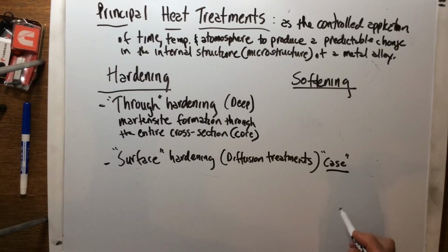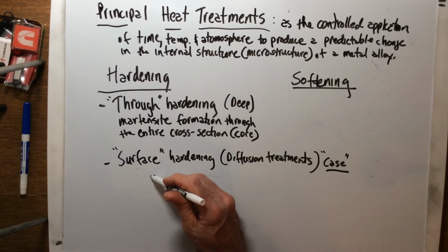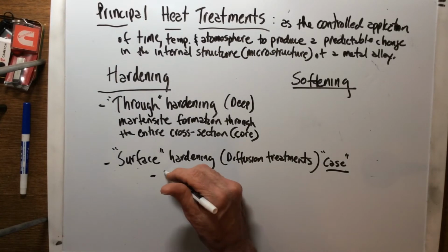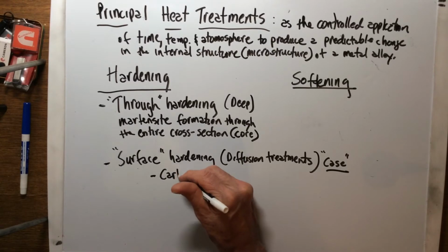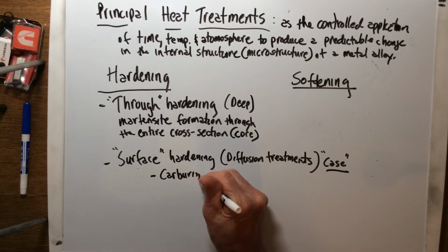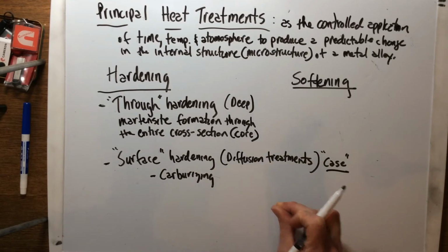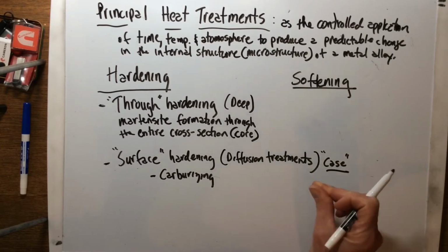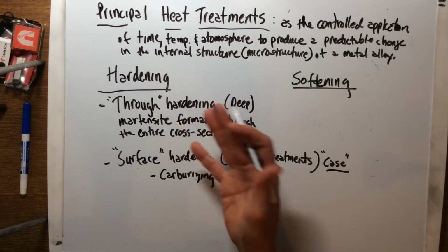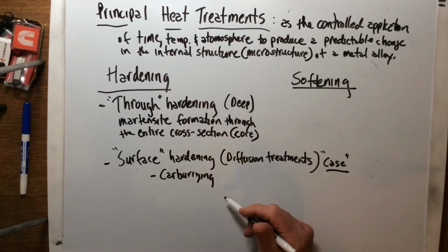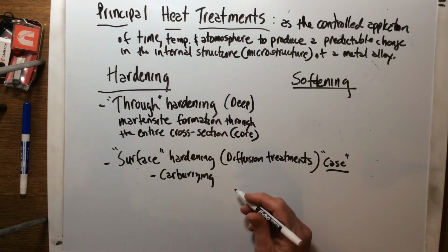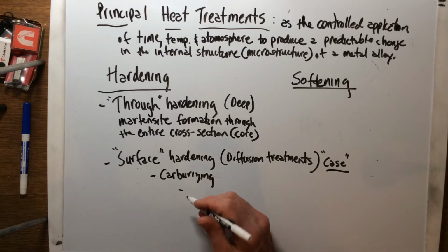and the first thing is a process called carburizing, and we've had this before too. Carburizing, which basically we're just diffusing into the surface of a low carbon steel more carbon to it, so it has a chance to be surface hardened. So carburizing has to take place, and there's really two ways to do this.